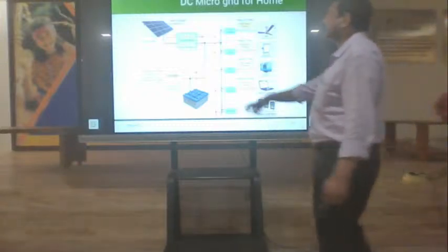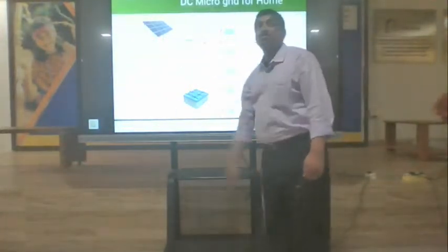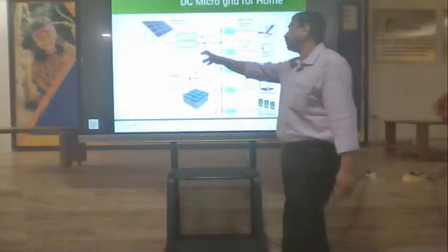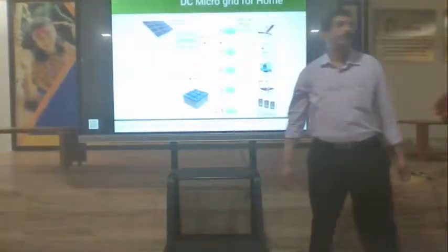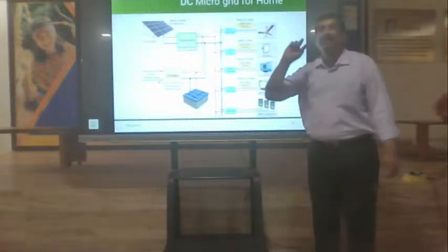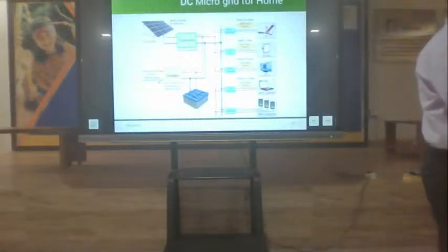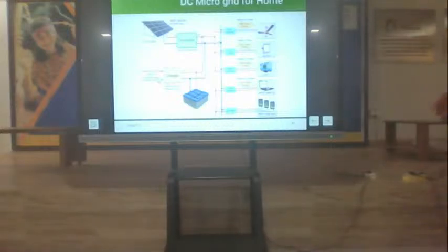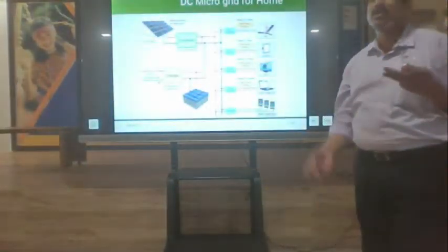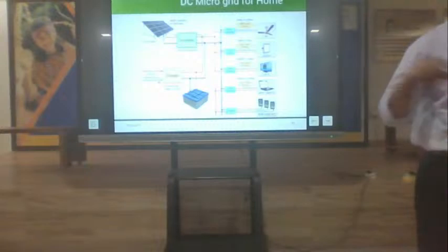So here what we are using is a switch mode regulator, an MPPT regulator. From the solar panel we give a DC and we get a regulated 24 volts DC supply. And then this 24 V DC supply... see, earlier if you had a ceiling fan, what was your earlier ceiling fan? Yeah, an induction motor. So what happens is you will have a line and neutral. Again, to create a rotational magnetic effect, you have to have a delayed winding which you develop with a capacitor.